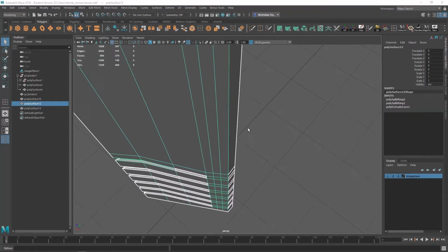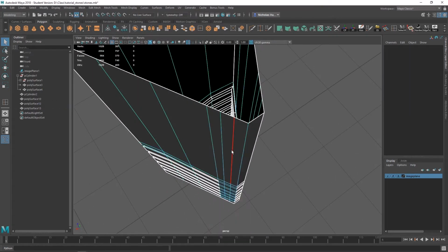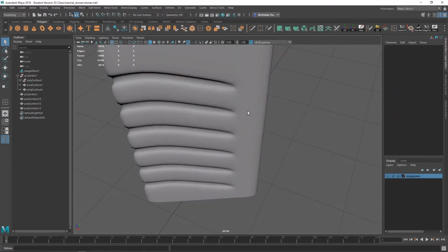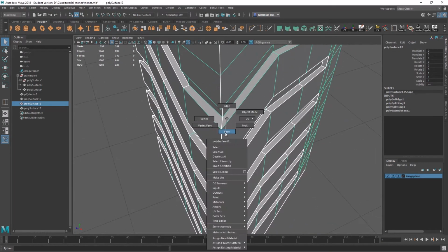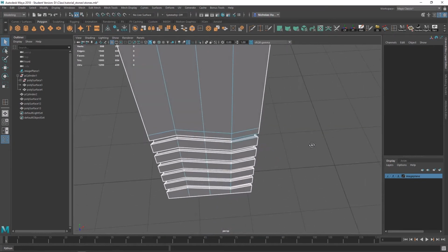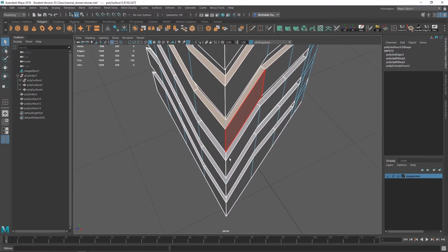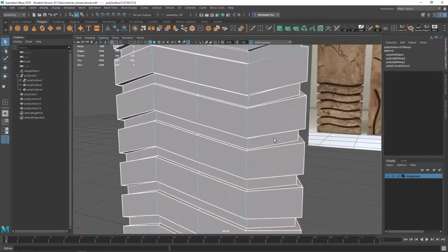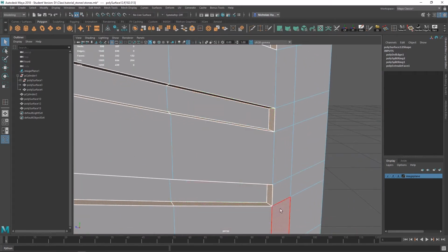And then because we're trying to just control these faces here, or these edges here when we smooth, we're just going to need this line. So we'll go to edge mode, delete that, delete that. And now when we smooth, that's a little bit better. It doesn't stretch so much. So now to really make that dug in, we're going to go to face mode, and looking down at about this angle so you can see everything, we're going to click once, shift, double click, with shift still held down, click, double click, click, double click, and keep on going with shift held down the whole way. Going to tap F to frame it, and you'll notice that when we shift double clicked, we selected this entire edge loop of all of these, and it wrapped around here, and all we have are those selected.